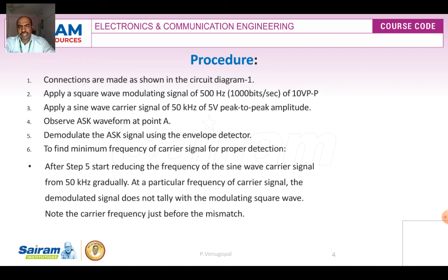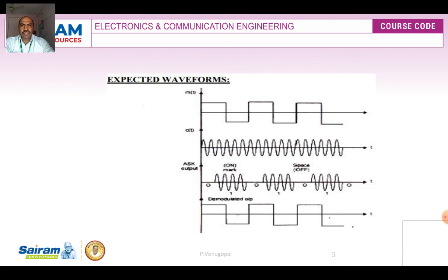Once you connect the modulated output as input to the demodulation circuit, slightly vary the potentiometer and set the reference voltage as 1.1 volts or 0.2 volts, definitely the output is obtained. The output has little distortion, but compared to analog modulation techniques, the distortion in digital modulation is negligible and very small. Let us see the waveform for this ASK generation and detection.